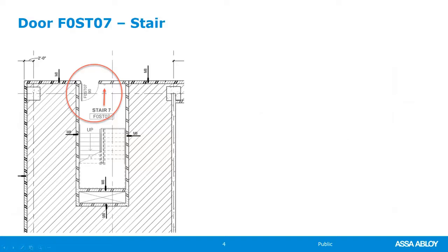This is the enlarged view. We can see that it is a 90-minute door. That makes sense because any building that is 4 stories or higher, all of the vertical exit stair doors will have 2-hour walls and 90-minute doors. Even though it doesn't say it, this little box right here, it should have the symbol CA for card access.